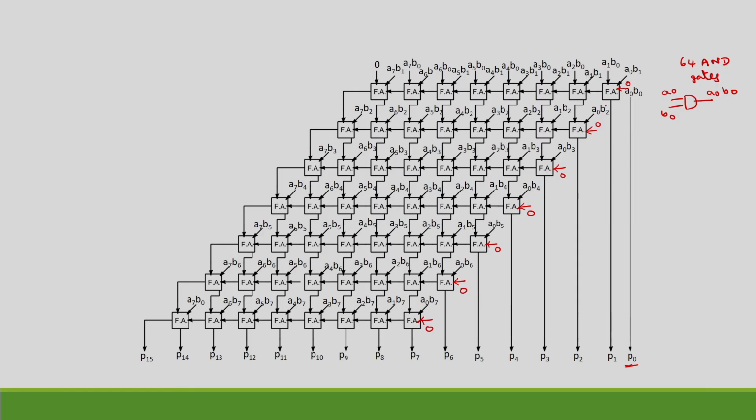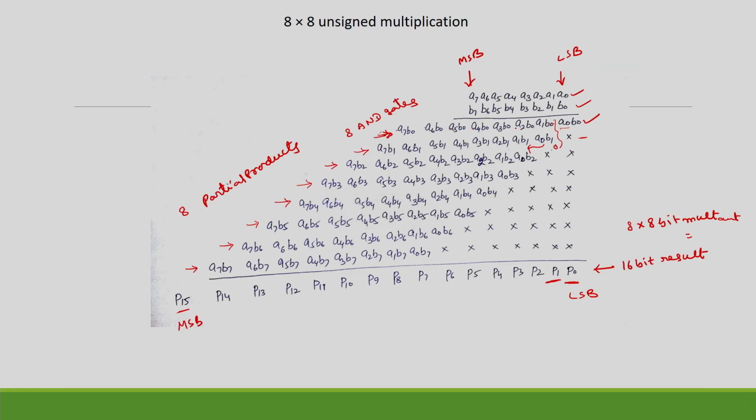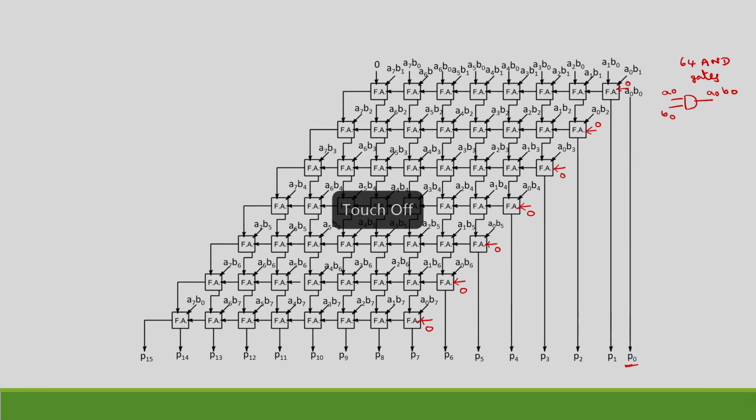In the 0 full adder, the sum bit is this. Along with this carry bit we have to perform addition of 3 more bits: A2 B0, A1 B1, A0 B2, along with this carry. So, that will be performed by using this. You are adding 2 bits along with the carry, then you will get sum and carry. This sum and the third bit, the other bit will be made 0. So, that you will get P2.